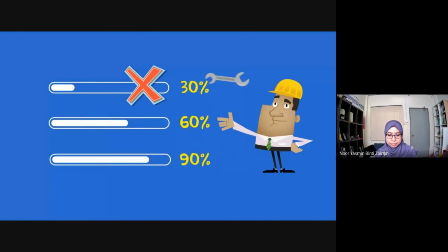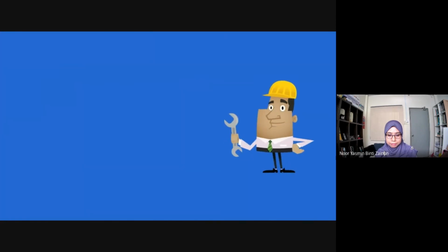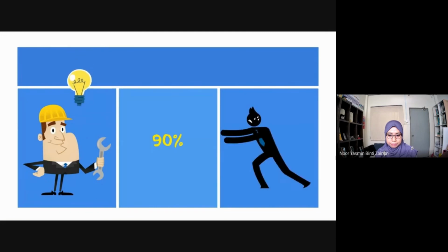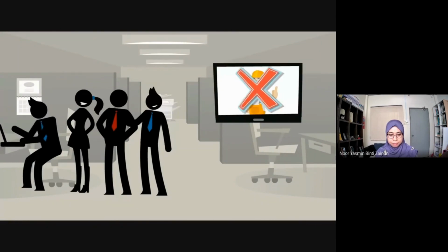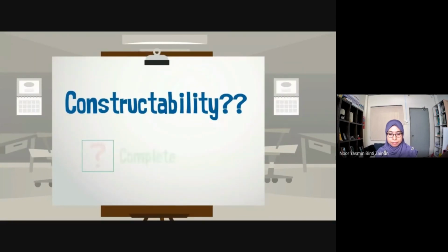Engineering invited construction to the 60 and 90% model reviews, but constructability is an ongoing process, and it's difficult to get good construction input in only a couple of meetings. And when construction came up with an idea at the 90% review, engineering said it was too late to change the design. No one appointed a construction subject matter expert to work with the engineering team to identify and mitigate construction roadblocks. Yet, the team said they did constructability.